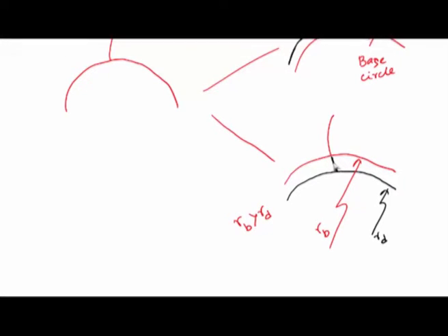Manufacturing processes will ensure that if the dedendum circle is actually lesser than the base circle, this black portion is basically just the radial extension. We extrapolate the profile, and that extrapolation is done radially, but definitely it is not going to be an involute. If at all there is contact in this black portion, then you are going to have a loss of conjugate action, and the fundamental law of gearing is going to be violated, and there are other repercussions in interference, as we will see.